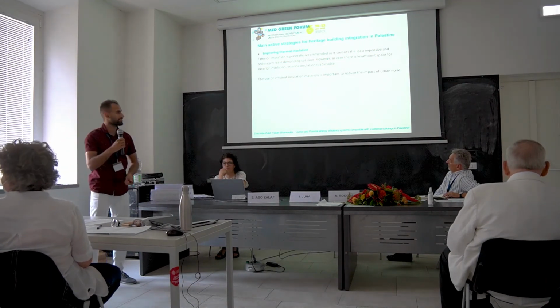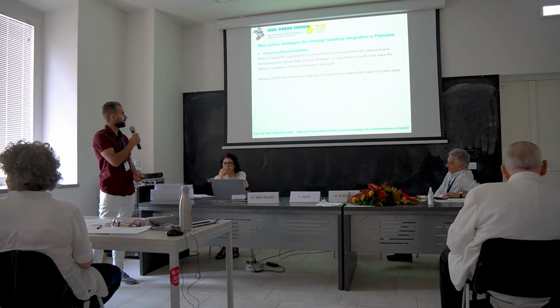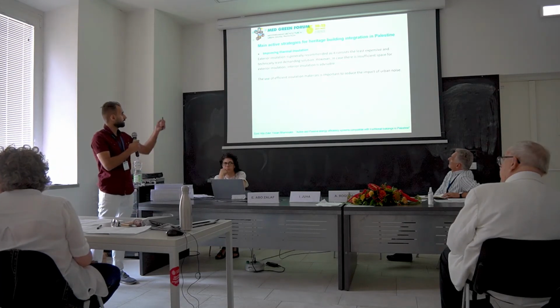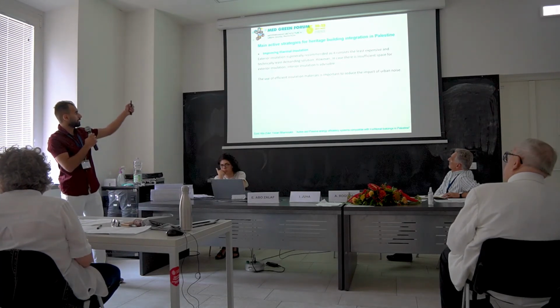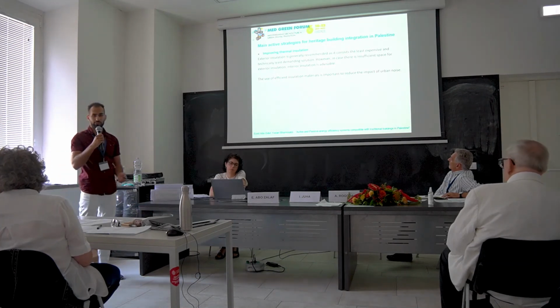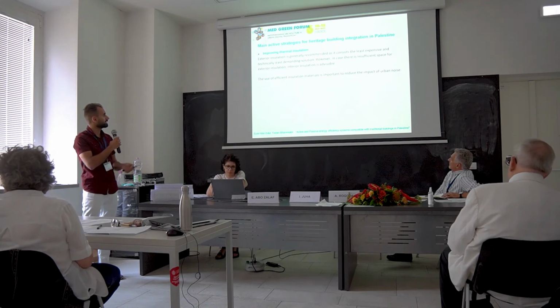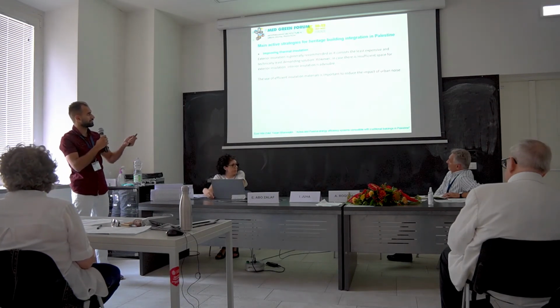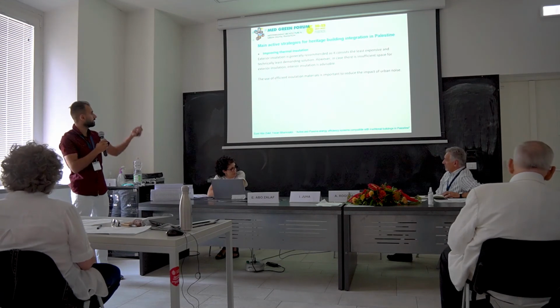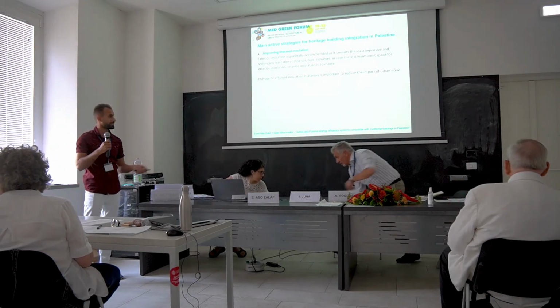The main active strategies for heritage buildings in Palestine. The first one is thermal insulation. Exterior insulation is generally recommended as it is the least expensive and technically least demanding solution. However, in case there is insufficient space for exterior insulation, interior insulation is advisable.